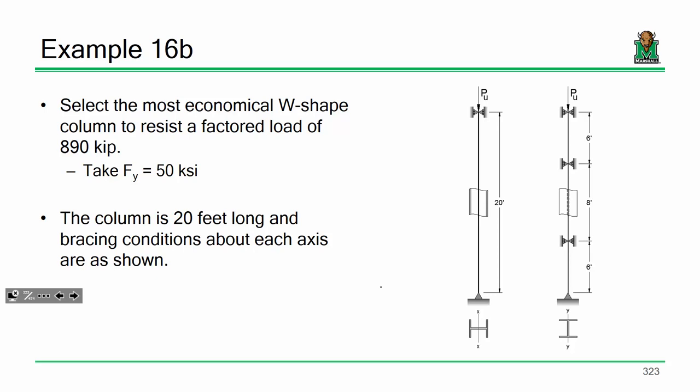If you can handle that, then honestly that'll remove just about all the confusion, because that's basically it. What I'm saying is that if I take this column and I apply load, there's a point at which it's going to want to buckle. It's going to buckle along the direction that has the longest slenderness, or the largest slenderness.